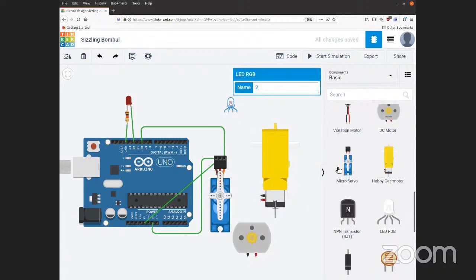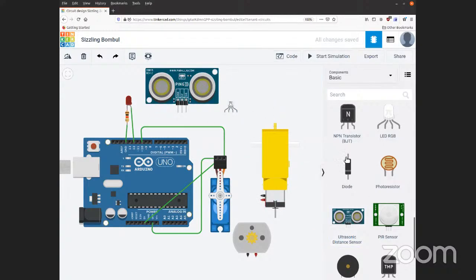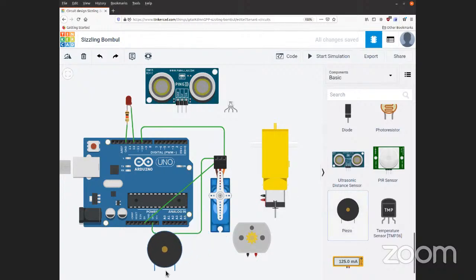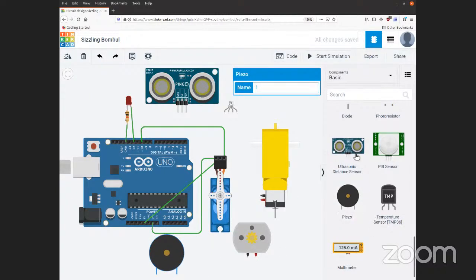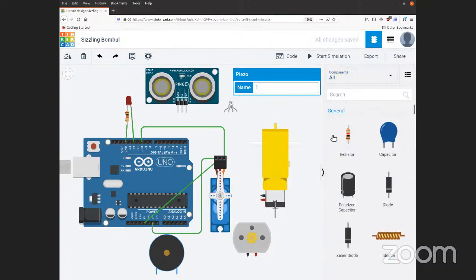Yeah, he's dragging DC motors on. What you'll learn in the DC workshop, as a little spoiler, is the Arduino is not strong enough to drive a DC motor on its own. So we have to use something else to get more power to it. And a servo is usually okay, so a smaller one. An LED is usually okay. Running sensors, they're usually pretty low power for most of them. But yeah, there's a lot of cool stuff you can use out there.